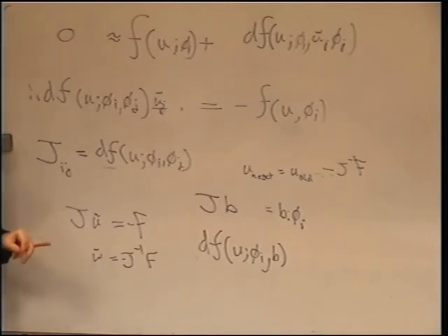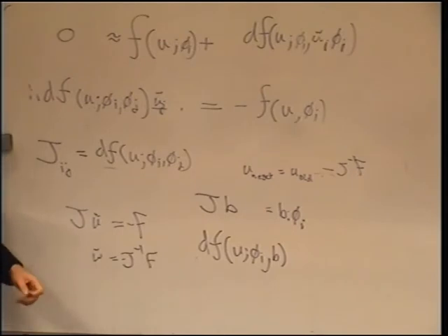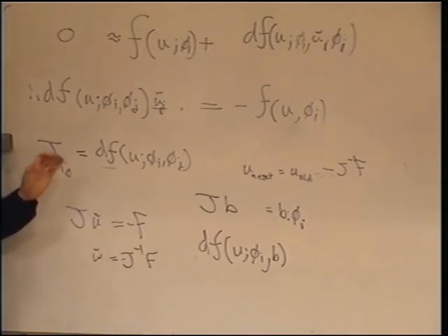There is a downside, and the downside is, if you know anything about preconditioners, which we're not going to go into here. Using the basic solver operations, so conjugate gradient, GMRES, all of those iterative solver methods only requires you to evaluate the function. Some of the preconditioners require you to look inside the matrix. So that's more of a problem. So that's a reason why you might not do it. So there's fighting back the other way.